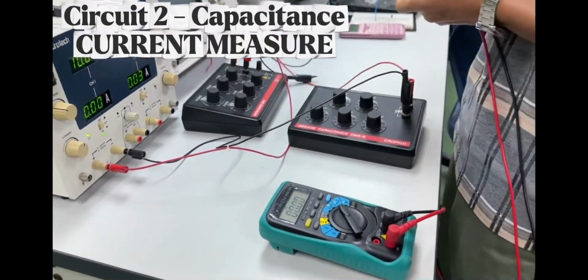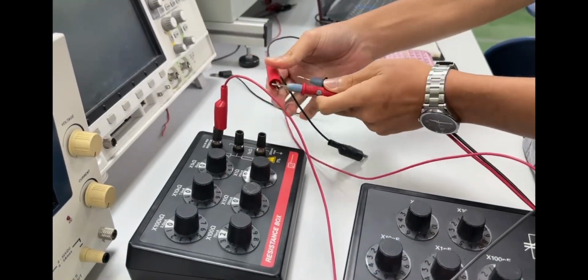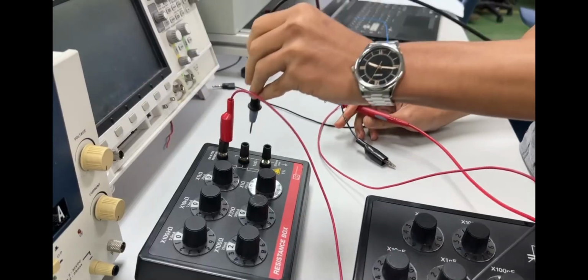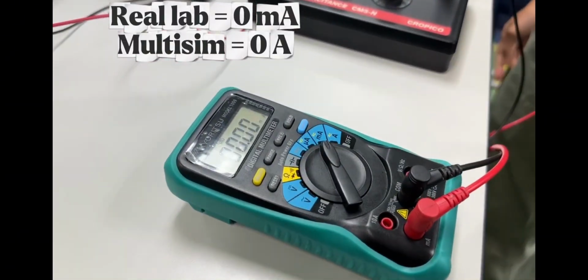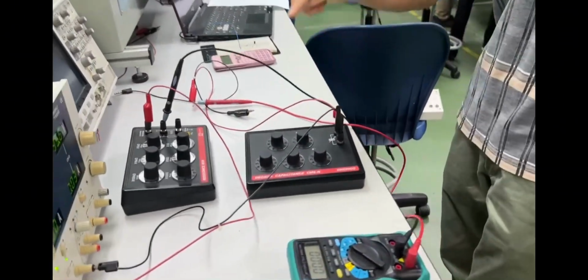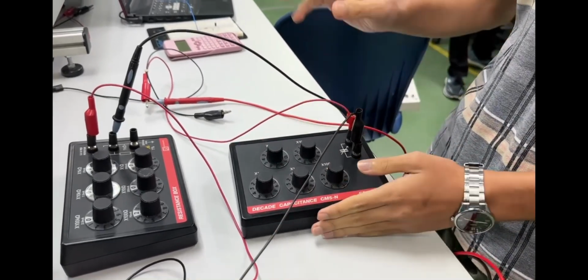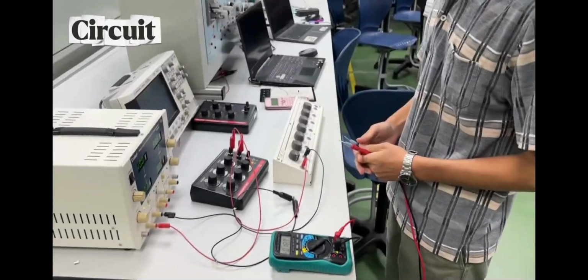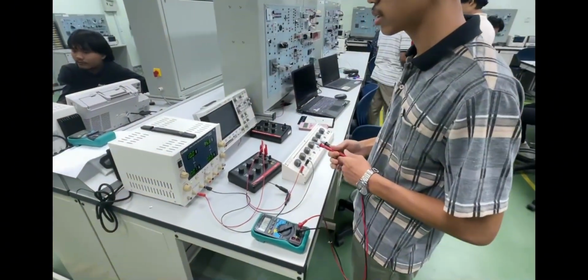First thing first, we need to put the multimeter here for the positive side and here for the negative side. As you can see, the measured value for the current in the circuit is 0. Why? Because the capacitor is fully charged, and when the capacitor is fully charged, there is no current flow in the circuit. I will demonstrate how to measure voltage and current for the initial circuit.